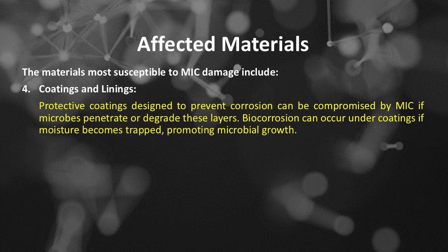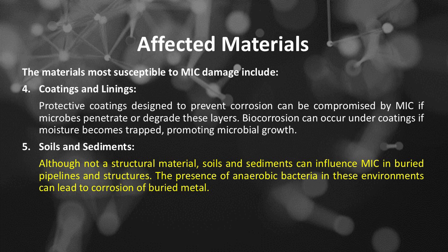Number 4 of the materials most susceptible to MIC damage is coatings and linings. Protective coatings designed to prevent corrosion can be compromised by MIC if microbes penetrate or degrade these layers. Biocorrosion can occur under coatings if moisture becomes trapped, promoting microbial growth. Number 5 of the materials most susceptible to MIC damage is soils and sediments. Although not a structural material, soils and sediments can influence MIC in buried pipelines and structures. The presence of anaerobic bacteria in these environments can lead to corrosion of buried metal.